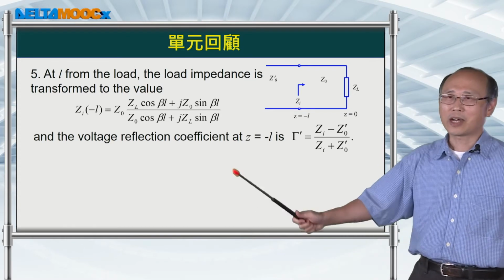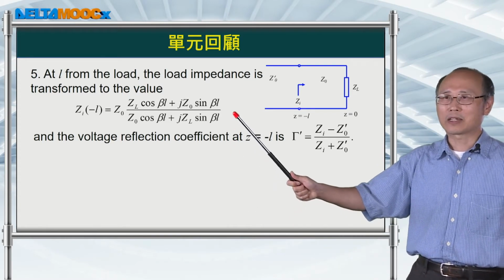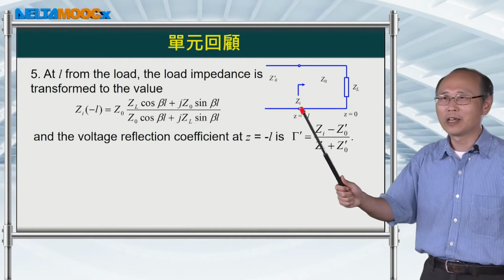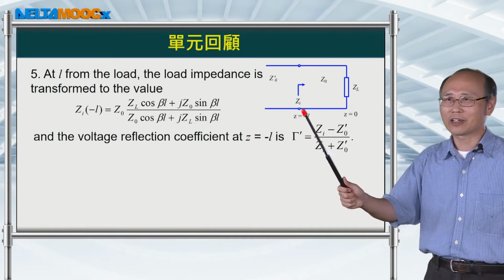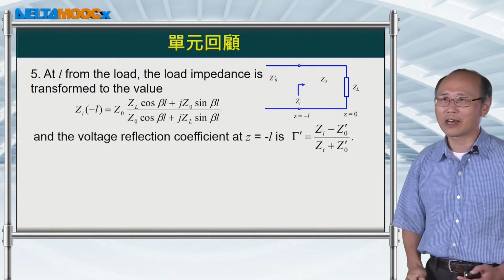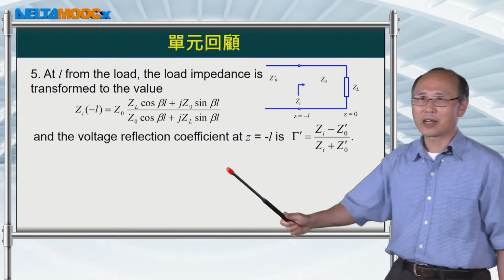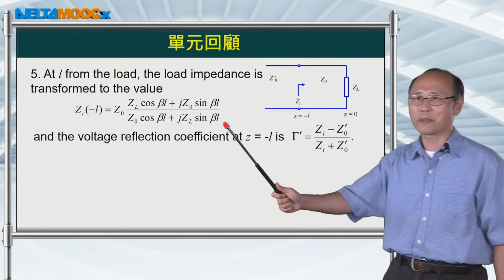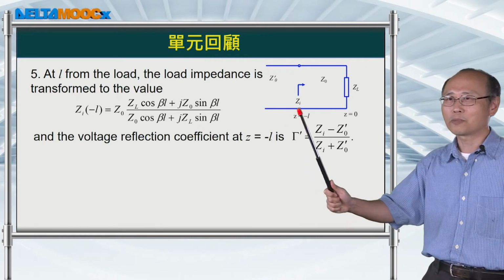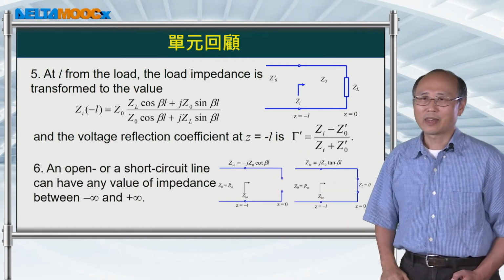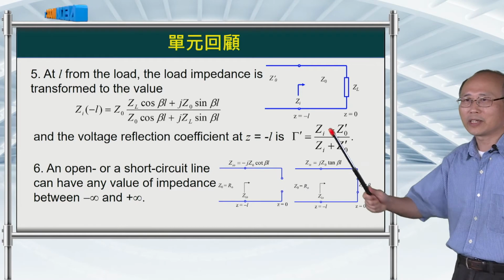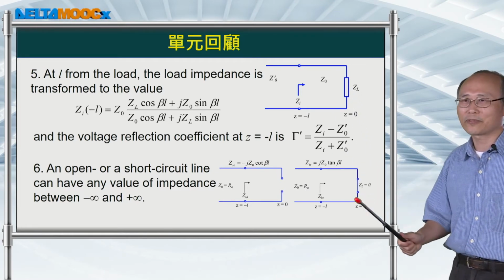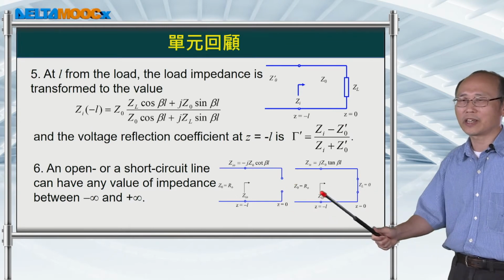And I also talk about impedance transformation, because quite often we need to know the reflection of a signal at a particular point on the line. So the impedance ZL is transformed into some other value given by this expression at this point. Then we remove this ZL, or replace it, to have an open circuit or short circuit on the line.